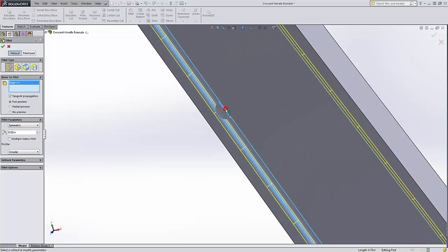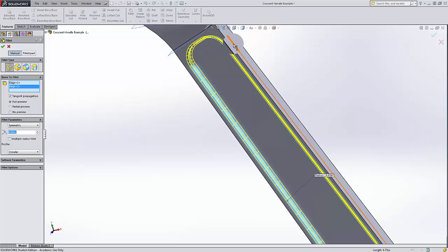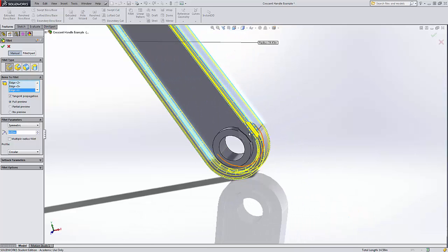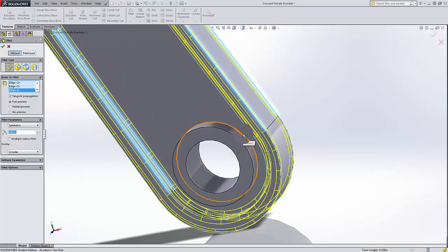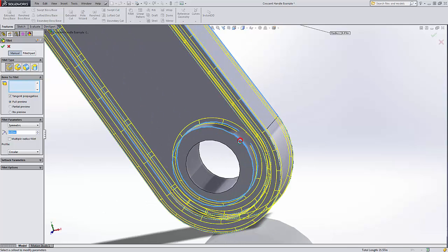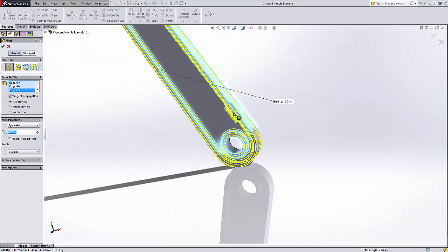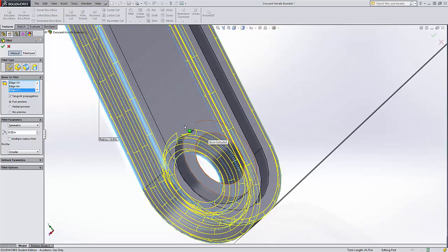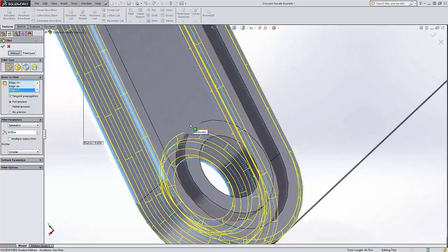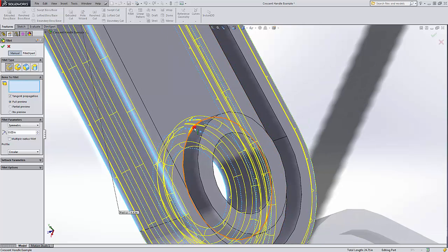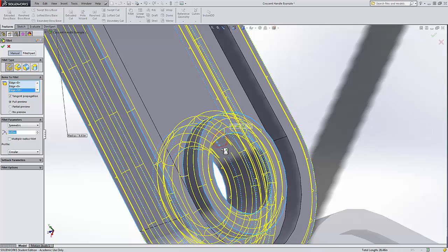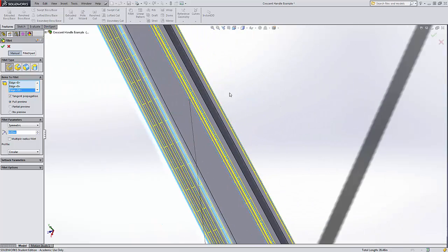And we're going to go in here, on the outside there, on the outside there, here. Now all these fillets are important because they can really help in manufacturing the actual part, and they will also reduce stresses in many high stress areas of a part.